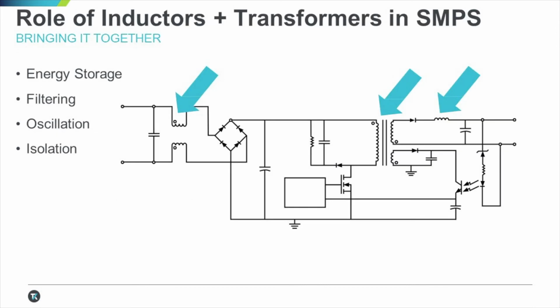It is expected that magnetic components such as inductors, coupled inductors, and transformers operate in stable conditions such that the power supply is not driven to an unstable condition. The stability is based on the function of these magnetic devices, such as storing energy, filtering, switching, and isolation. Ultimately, switch mode power supplies can be made smaller and more efficient by operating at higher switching frequencies.